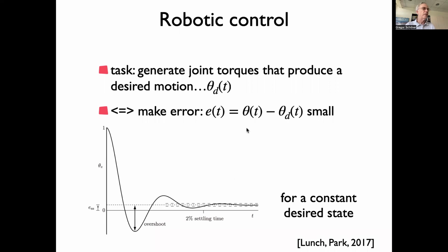And so when this error is small, you could derive from it in which direction to intervene. For instance, if it's positive, that would mean your joint is further along the defined direction than you want to be. So you insert into your control circuit a torque that goes in the opposite direction, and in the next moment in time, you would have reduced that error.